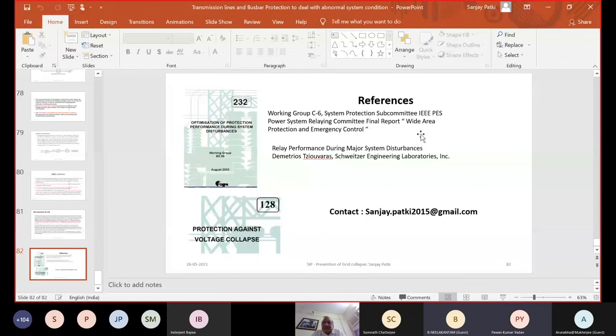Yeah, but if it is a single circuit evacuation of a small generating station, which is the case here, actually it is a pump house from our generating station. We are charging that pump house around 30 kilometers from here, and we have implemented the open conductor system in our 33 kV system. Whenever we are charging the transformers at our pump house, like distribution transformers, 6.6 to 415, all these small transformers, our line is getting tripped on open conductor faults.